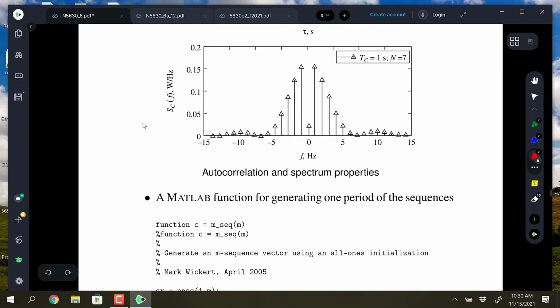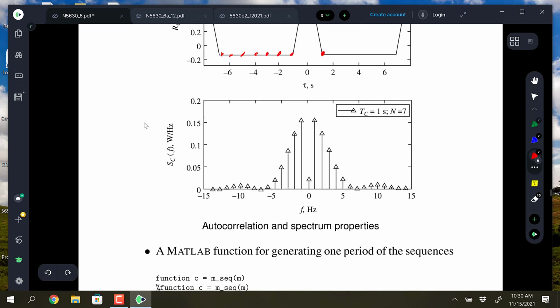Okay, the choice is you add a number from 0 to 1.5, right, and then round. And so we use very long Gold codes for that, so that we don't have any autocorrelation in our rounding. That makes sense. You want to be very precise. Well, yeah, because you don't want autocorrelation in your rounding, because then you get nonlinear, data-dependent rounding, right? So anyway, we do things like that where we have to kick it off at some point.